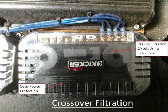Because we are dealing with several different kinds of speakers, the signals sent to each are tailored specifically for them. This signal filtration began at the head unit, had low or high pass introduced at the amplifier, and finally will be component specific after passing through this device. This is called a passive crossover network, and it separates the amplified signal into mid-bass and tweeter-friendly levels.